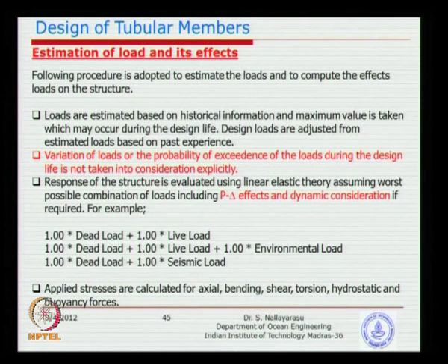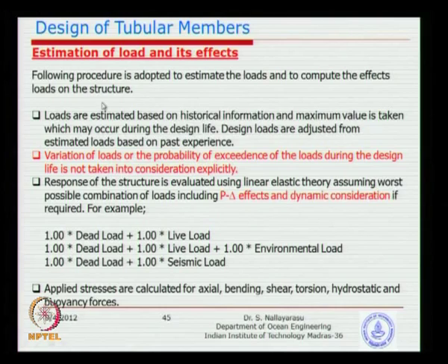Now, if you look at the load effects, how do we normally evaluate them for the allowable stress method? It is basically looking at what was done in the past, from history, with a few examples. Residential building, you design for 500 kilogram per square meter. You design an offshore platform, probably several past examples of design will be available. So, based on that information you look at the loads and estimate using past experience.